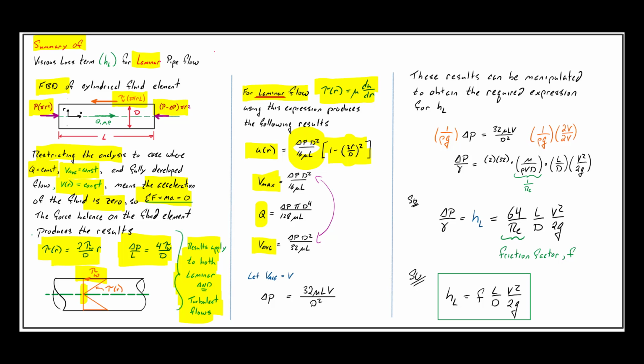And then we have an expression for the change in pressure. So within a circular pipe with laminar flow, constant flow rate, we're now going to have an expression for the pressure drop. And I could divide these both through by L, and that would give me the pressure drop as delta P over L, but we know that this is a linear pressure drop.